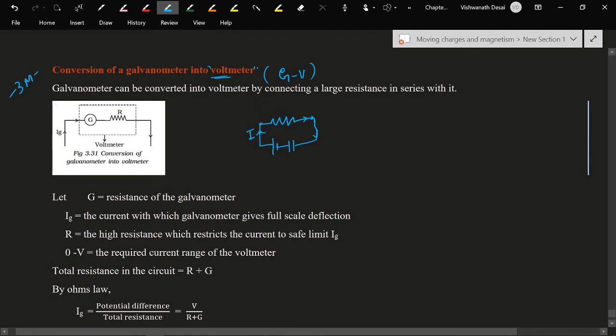Now I want to calculate the voltage or potential difference across the resistor. So the current is always through the resistor, but potential difference is always across the resistor. So across means we need to connect the voltmeter always in parallel with the circuit across the resistor here. Then this voltmeter will measure the voltage across the resistor, to be connected in parallel with the circuit like this.